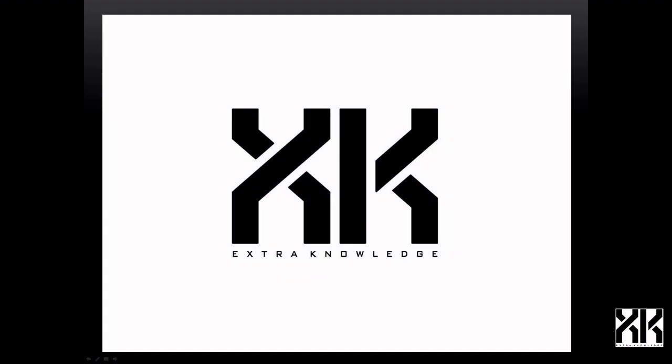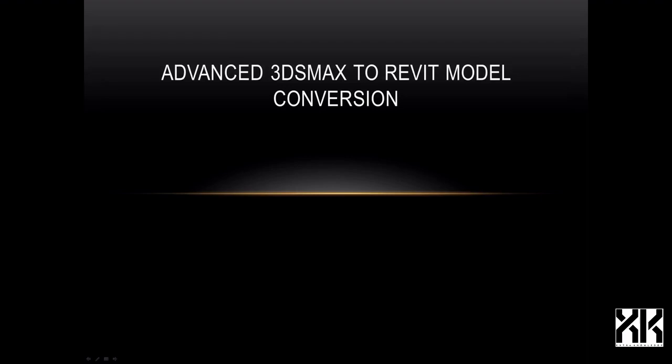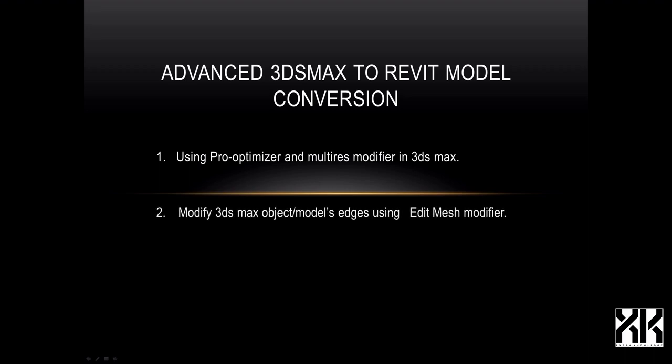In this tutorial, entitled Advanced 3ds Max to Revit Model Conversion, we will discuss the following. First, using Pro Optimizer and Multires modifier in 3ds Max. Second, modify 3ds Max objects or models edges using Edit Mesh modifier. Third, setting detail level in Revit.